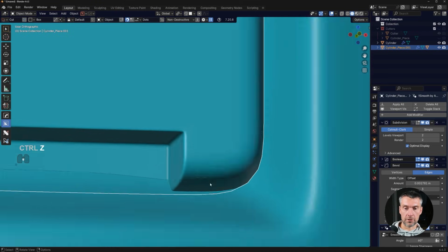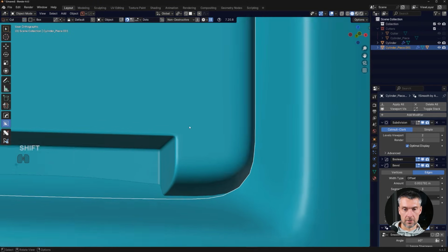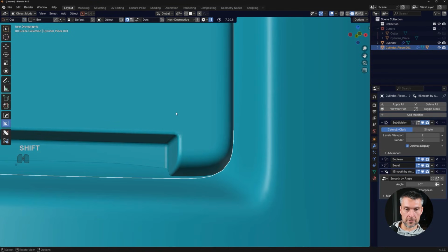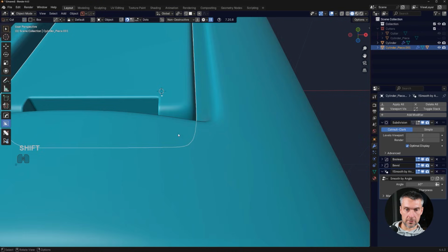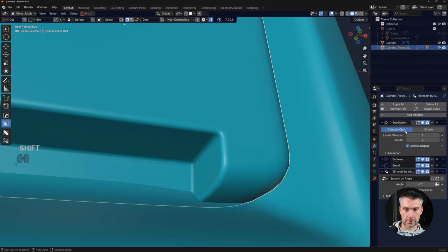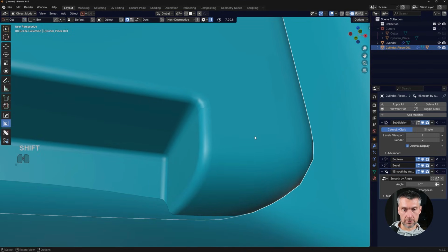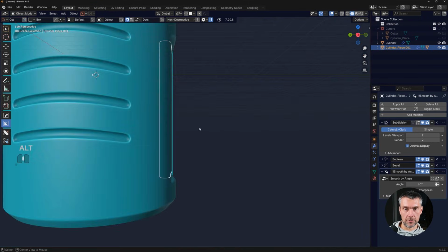So what you would need to do at the end is apply the bevel, and then fix this topology here. So that's how you could go around and sort of fix this problem, right? But honestly, we're not going to be doing that because I don't think there's a point. Another way of doing this will be to apply the subdivision, apply the boolean and the bevel, right? And then run subdivision at level 2, then fix this corner here by connecting topology, and then run one more subdivision on top of it, okay? But this is going to be destructive, so this is the only problem, right?